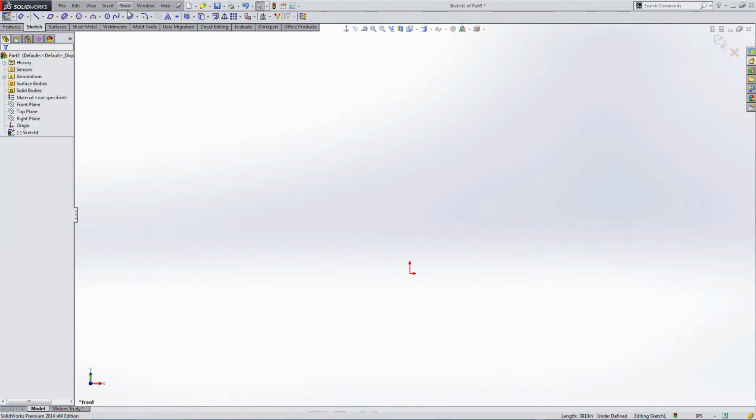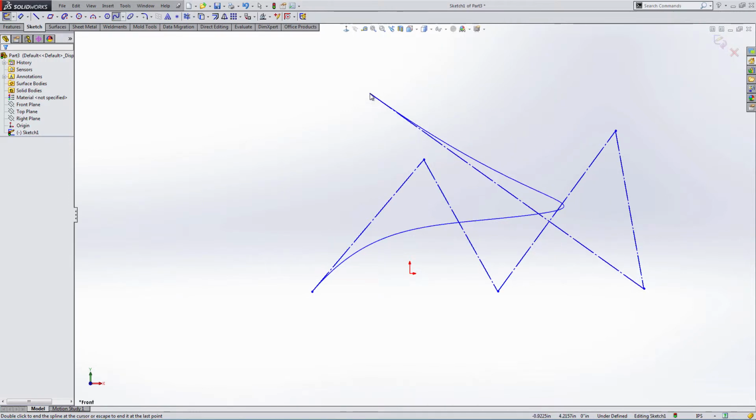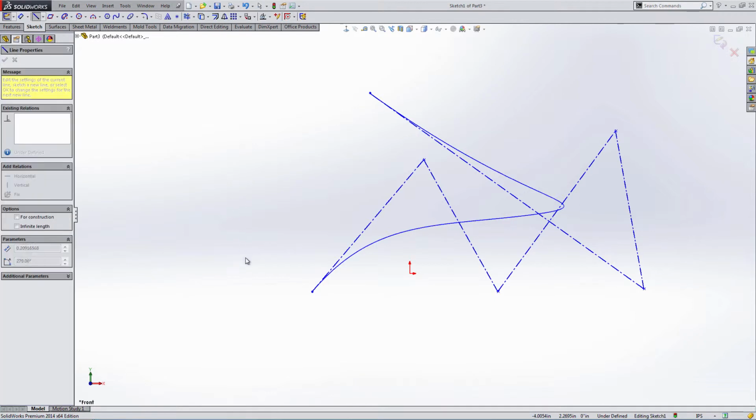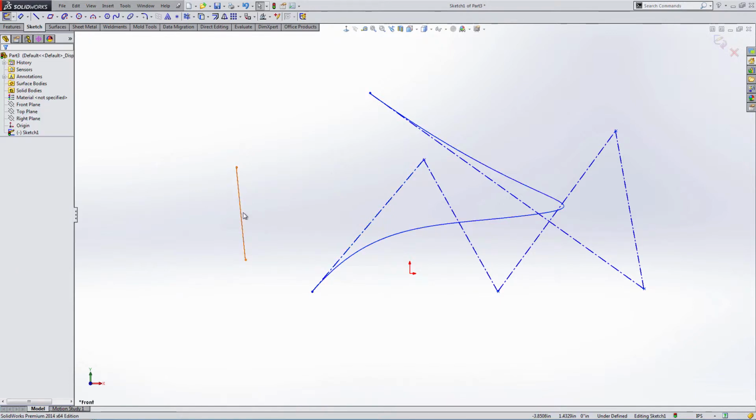And then there's a style spline, which is new for either 2014 or 2015. And it's a little different. You can actually dimension to the controls. So I could set these two parallel. Actually, that's wrong pick order.